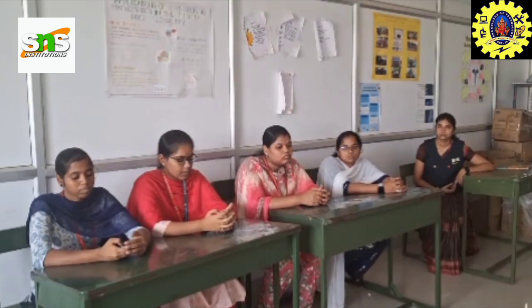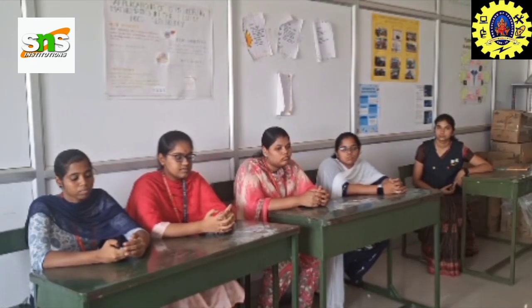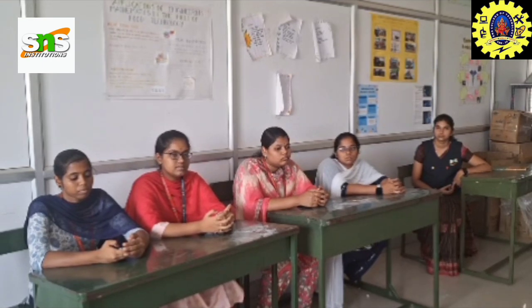Green material under construction techniques. We have 5 techniques: recycled material, sustainable wood, low VOC material, insulated concrete forms, green roofs. Recycled material: using recycled material such as recycled wood, recycled glass and recycled metal to reduce waste and conserve natural resources. Sustainable wood: using sustainably sourced wood such as certified wood to promote responsible forestry practices.